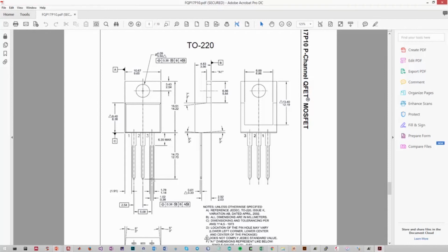The other thing to be aware of is the width of the pin legs, because they will determine the diameter of our through holes. So this inner width here is 0.38 millimeters to 1.02 millimeters. So we need a hole that can hold at least right around 1.02 millimeters. The convention for the TO220 transistor standard is right around 40 mils in imperial units, which translates to roughly 1.02 millimeters. So we'll be using pitch spacing of 100 mils and a hole diameter of 40 mils.